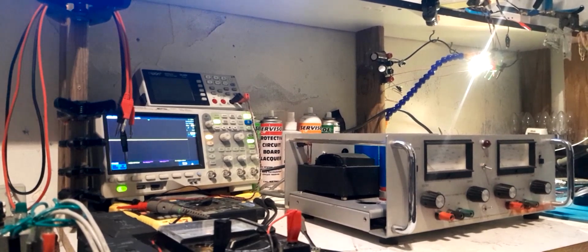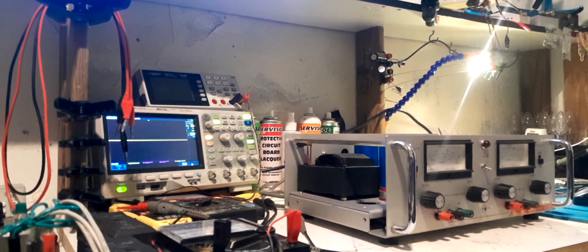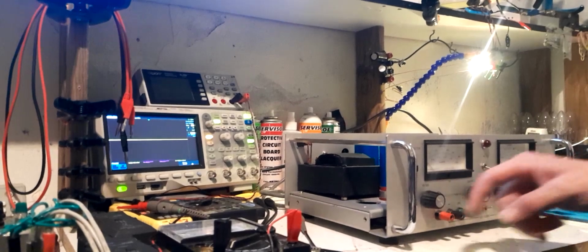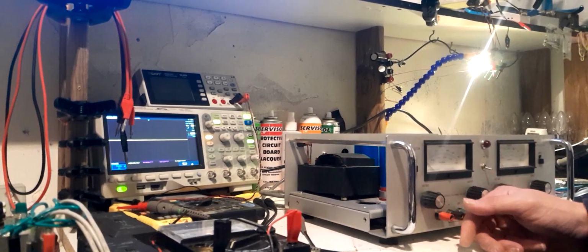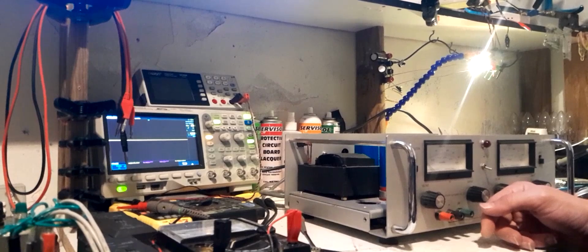Anyway, like I said, the voltage supplying the dropper resistor and the current across the reference don't actually disappear when it goes into oscillation, so it's not a current problem. But for stability reasons, I'm thinking, if I can't make one of these rock solid, because like I said in the last video, I can't just keep going up in capacitance, because there's a dropper resistor that drops the current into the TL431.